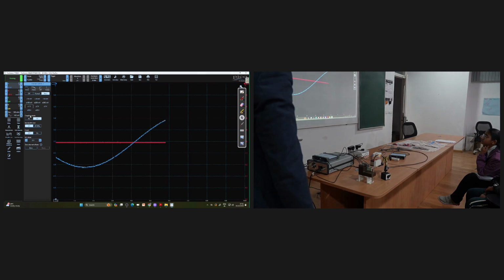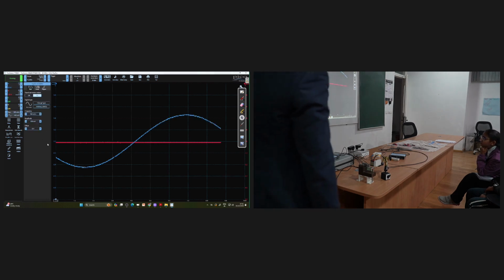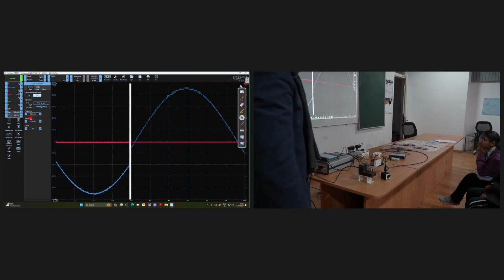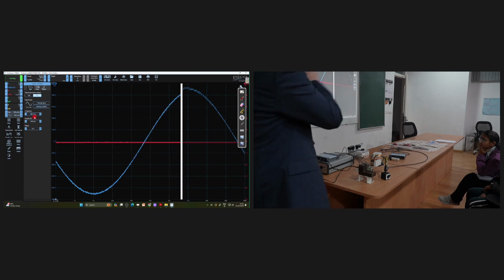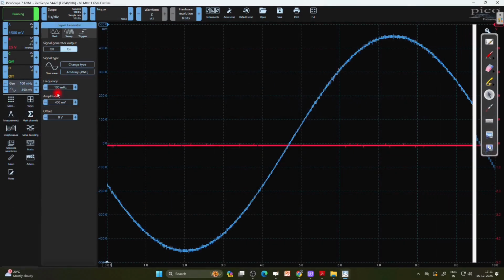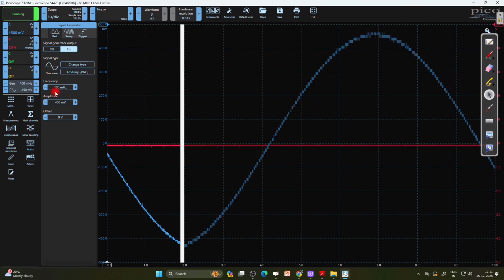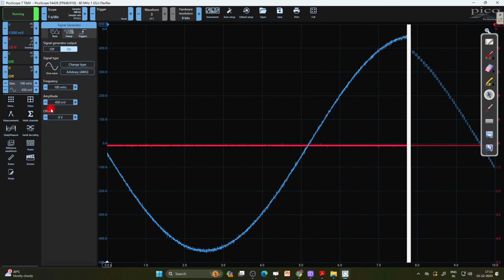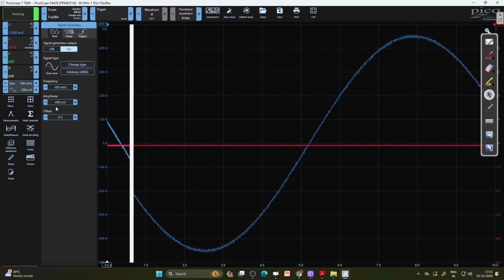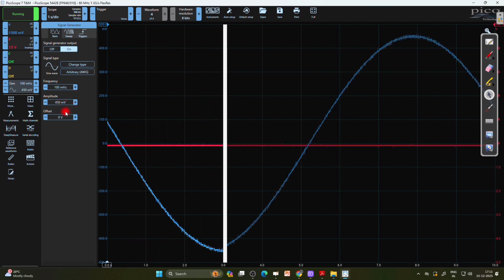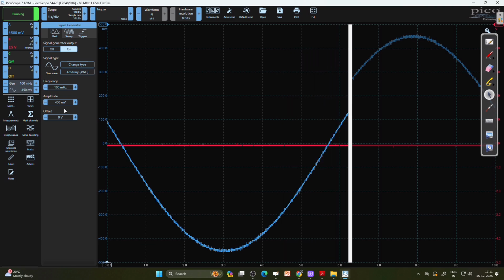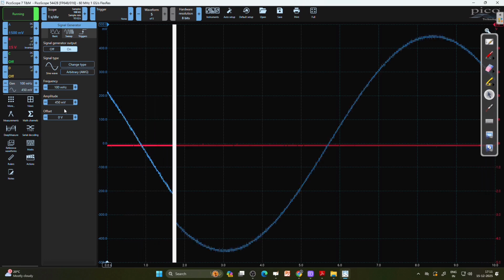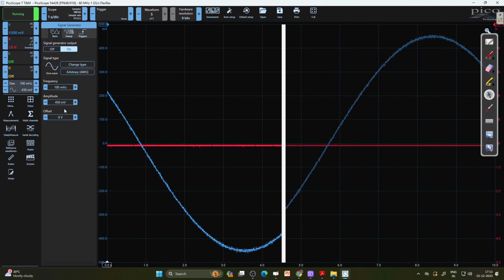What I prepared is, I used a very small frequency of 100 millihertz, not megahertz, millihertz, so 0.1 hertz. So very slowly, we increase the voltage, we decrease the voltage, and we shift between minus 450 and plus 450 millivolts. So that's the amplitude, right? So this is what you can now see, since I connected the signal generator output to the input channel A. You can see on channel A what the function generator outputs. And on channel B, you just see what the laser distance measures.